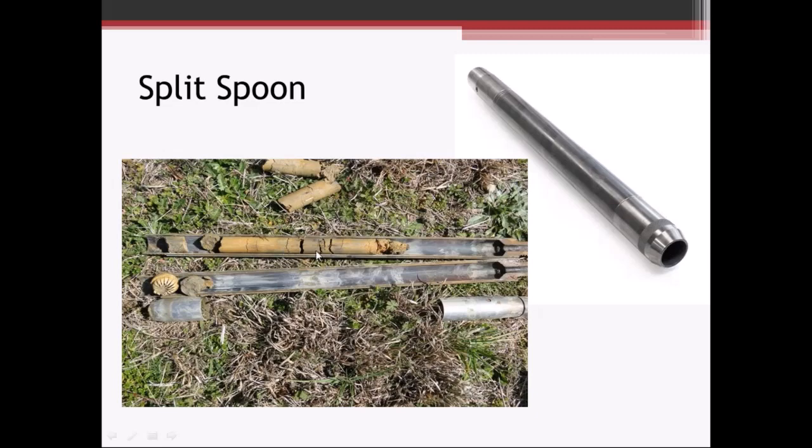The other limitation is that we're typically collecting small amounts of sample. So if there is a gravel material, the sample size may not be in accordance with the ASTM test procedure. So once the samples are collected, you can open up the split spoon and then take the sample from the interval specified by the engineer and seal those up and send them into the laboratory.